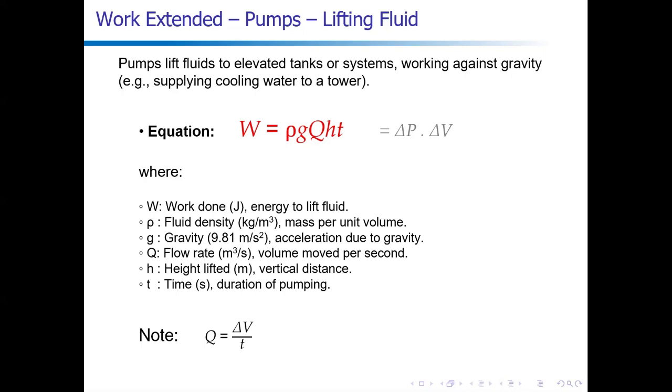This version is often more useful in systems where you don't have a pressure sensor installed, or you care more about the energy required to lift water, rather than the pressure drop. Or you're working in an open tank or cooling towers where pressure is atmospheric, and height is the only thing that matters. It's also common in pump design and energy efficiency analysis for water utilities and cooling systems.